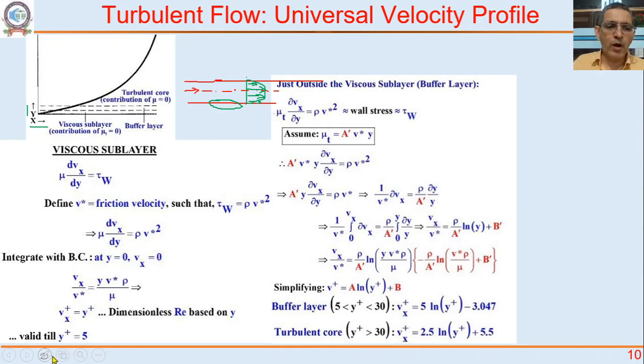So near the wall, velocities are small. If velocities are small, can we say the Reynolds number is small? The local Reynolds number is like 1, right? So your flow is laminar there. Near the wall, this is the bottom wall of the pipe, the flow is laminar.